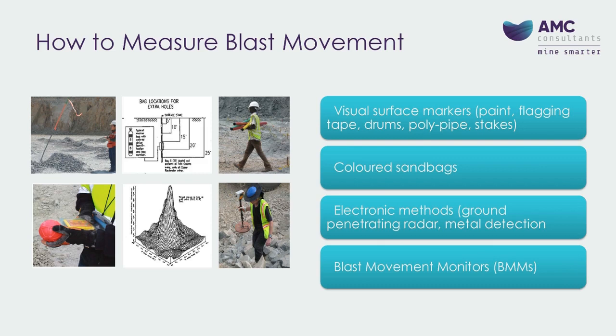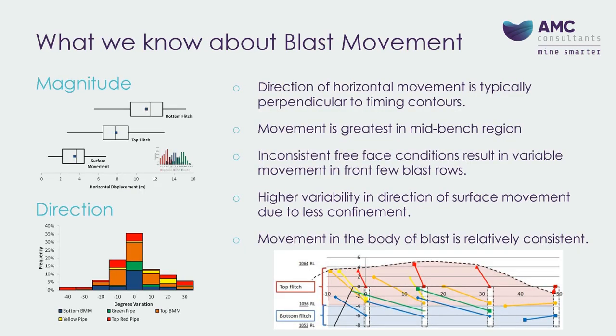The advantages of this system are measurement of subsurface movement, and multiple BMMs can be used per hole. They are more accurate and reliable with increased detection rates, usually documented to be around 70, 80 percent upwards. And they can measure blast movement quite easily to depths of 20 meters. Disadvantages of this system, there aren't many, but they can be time consuming to implement in the blast prior to blasting, and there's obviously a cost involved in using this system.